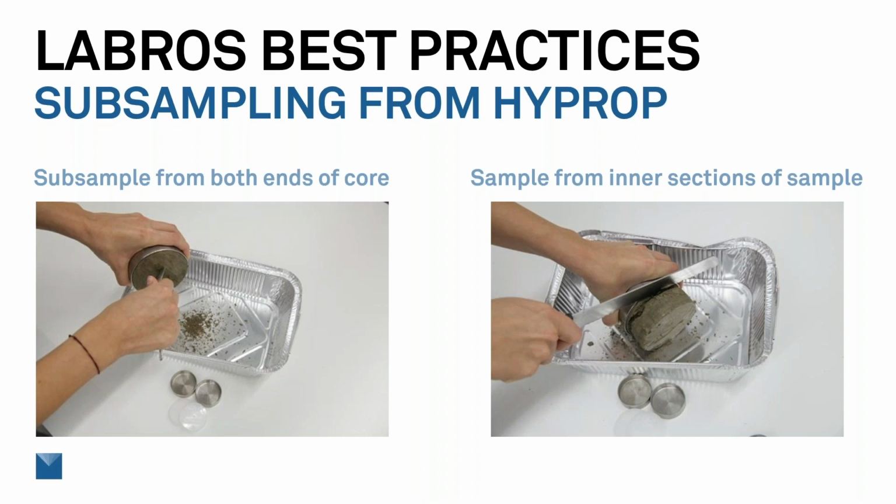And then we start pressing the sample out of the core and dissecting it into different sections, usually 2 or 3 different sections, and trying to collect intermediate samples at those 2 or 3 different points. What that does is it gives us several samples along the drying curve. And then we can easily take those samples and run those measurements in the WP4C and get really nice matching of our retention curves from the 2 devices.